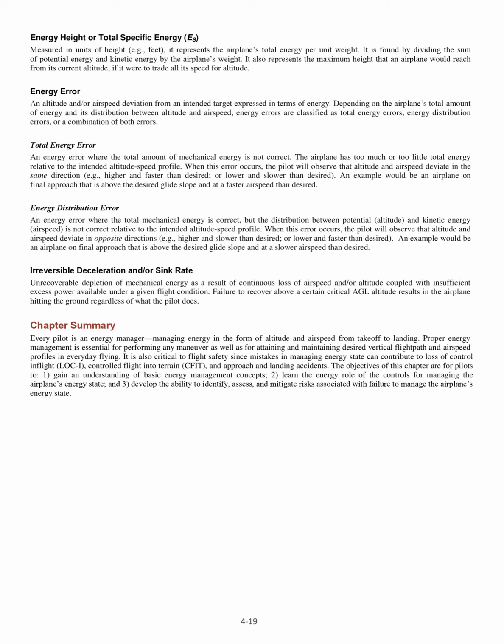Irreversible deceleration and/or sink rate: unrecoverable depletion of mechanical energy as a result of continuous loss of airspeed and/or altitude coupled with insufficient excess power available under a given flight condition. Failure to recover above a certain critical AGL altitude results in the airplane hitting the ground regardless of what the pilot does.